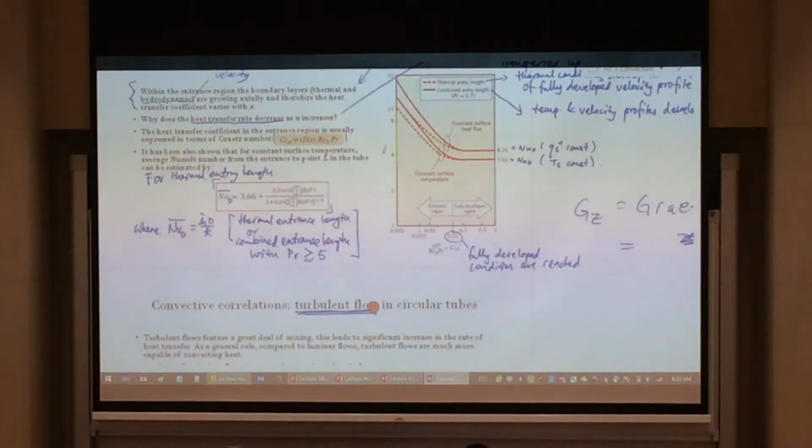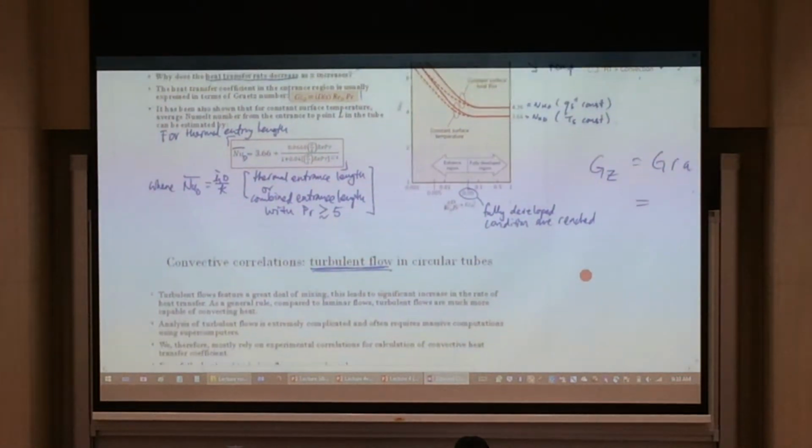How does that turbulent flow come about? Your fully developed flow, due to the viscosity, somewhere along the line there might be bends or surface roughness. That's when your fully developed flow will start to churn up, and then it will develop into turbulent flow. So most of your pipe system, unless you have very smooth pipes, will experience turbulent flow after some point of time. There will be those turns moving around, and soon after you get turbulent flow.